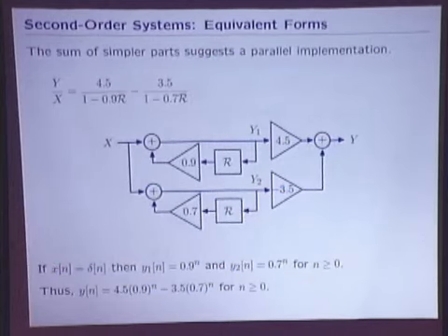Everybody's with it? So it's even better than being able to cascade, where in the cascade, we have to do some complicated bookkeeping in order to figure out the responses. By thinking about it with partial fractions, it's the simple sum of two simple things. So then if you know properties of each individual one, like it rattles for a long time or it decays quickly, you can instantly say something about the combined response. Does that follow?